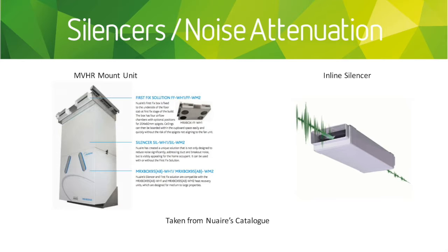Noise is measured in decibels, but the key one to look at is the NR level. The NR, because all your ears hear sound at different frequencies, at different levels, and perceive it all differently. So the NR level tries to put this into context by using logarithmic curves. The NR level for a home, or in a bedroom, should be around about 30, and in other areas it could have a higher NR level. But if in doubt, please speak to the manufacturer.